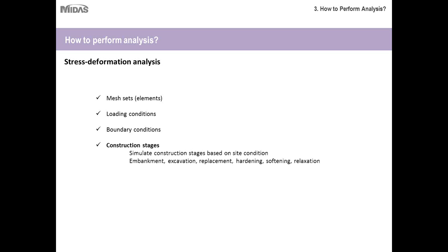So construction stage is useful for simulation of how the actual site or the structure was constructed, and this includes the steps of excavation and installing different components. And why we are doing this is that we want to capture the stress history of the soil strata and the structural members. So if you can recall from a couple of previous sessions when we talked about the importance of construction stage analysis, there you would have seen how the stresses and deformation vary in contrast to the static analysis.